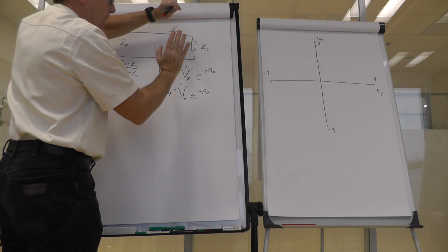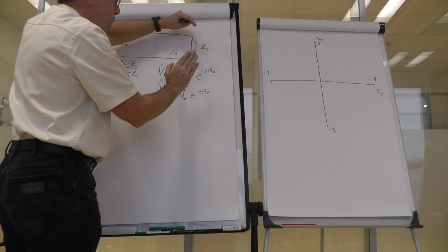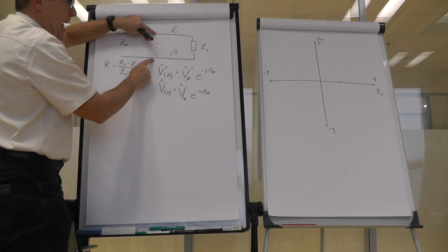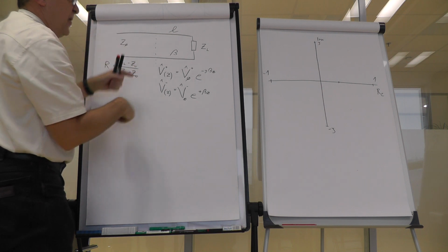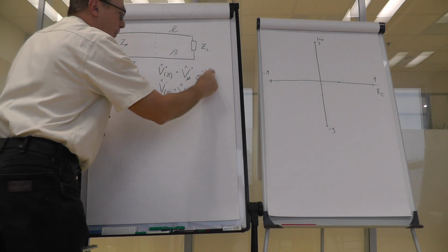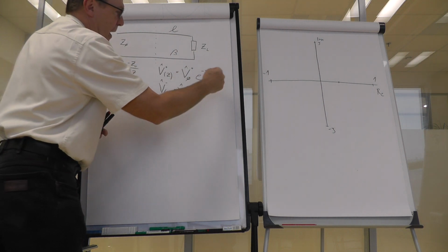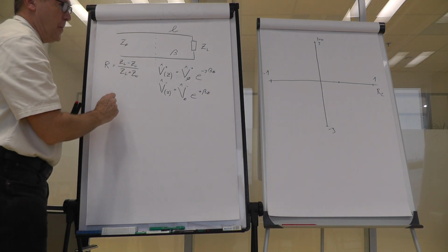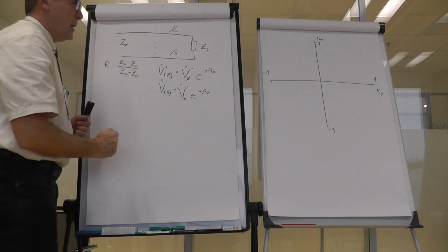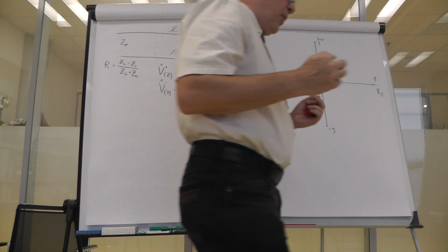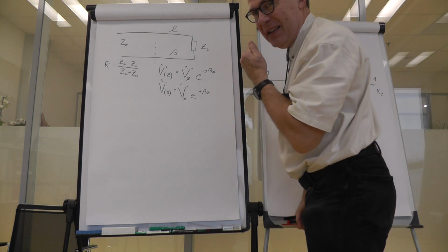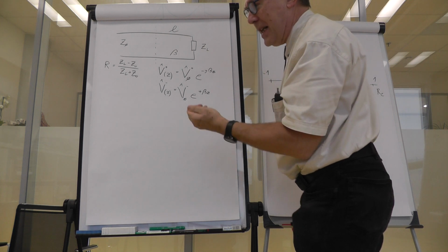So what if, for example, we slide for, let's say, 1/4 wavelength? If this is a 1/4 wavelength, the phase difference between the incoming wave and outgoing wave is 1/4 and 1/4. So we would have 2/4 of a wavelength, which is 1/2 of a wavelength, which means that we have just antiphase.